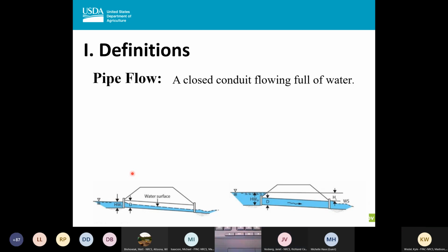And Janet, when you check both and you have two answers, which one do you go with then? Sure. As Doug said earlier, you go with the lower one as the controlling one. And then Kyle, I think probably later on, you're going to mention when you have a drop riser, you have a high orifice and a low orifice, the low one being the outlet pipe, and the high one being the riser itself.